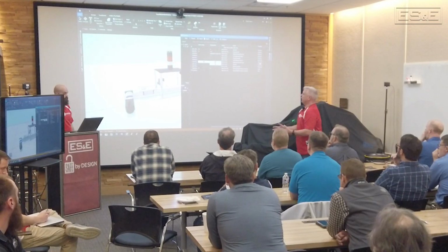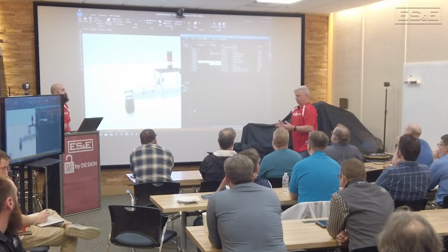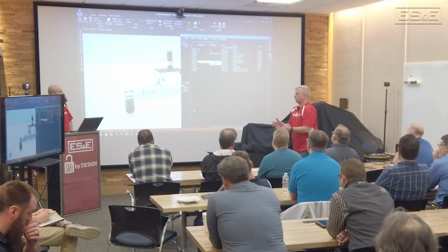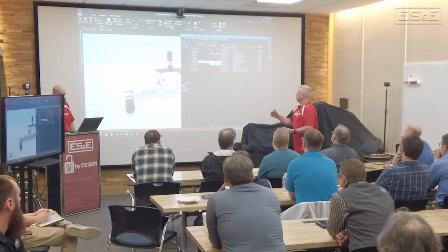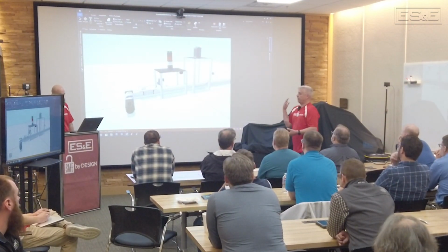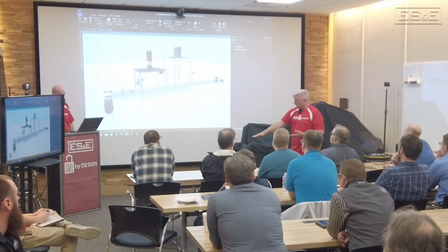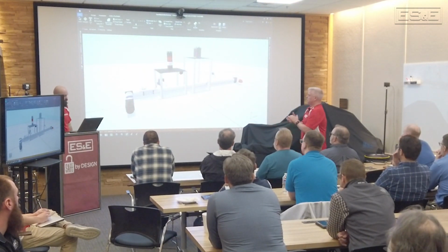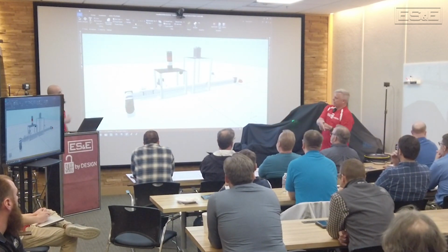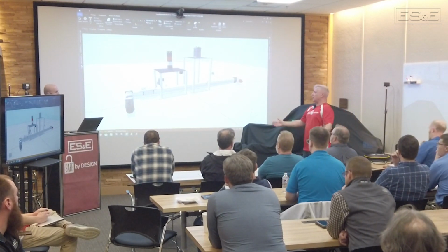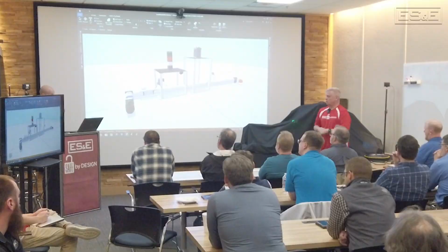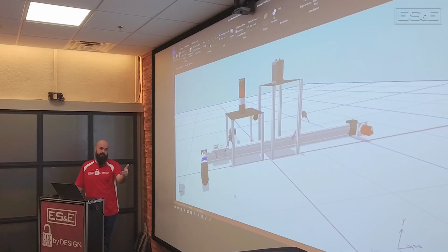the PLC. So what we're saying is instead of actually having to have physically a PE tied to something and having it go high or low, however it's set up, we can have Emulate3D say, okay, you're blocked just simply because you've blocked the path of the photo eye. Exactly. And that will drive that tag inside the PLC to move on to the next step, is what I think you're saying. Yep. And it's actually going to operate the same way that your physical device will. Nice, okay.